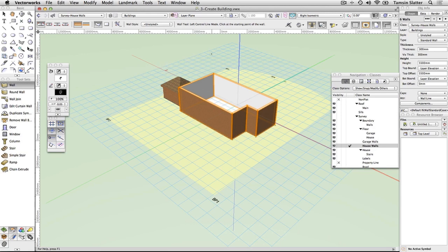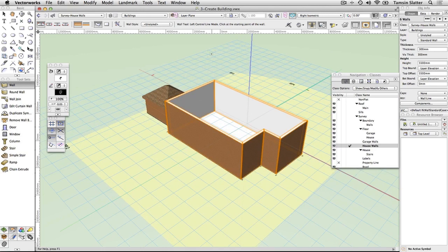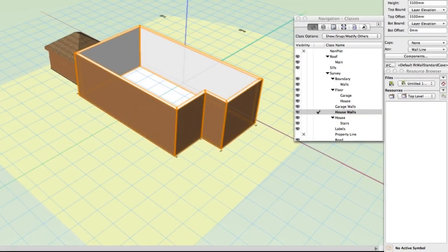Insert doors. The door and window tools, also found in the Building Shell toolset, have a Preferences button on the toolbar that allows you to configure a wide variety of door and window styles. These can be inserted into walls at the correct position to properly represent access to the landscape and to represent the building in 3D. On the resource browser, click the Home button to the right of the palette to ensure